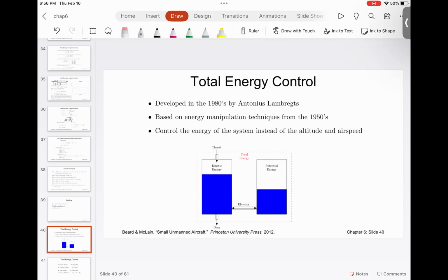That is, you fix the value of KD, and then adjust the KP so that it gets to the desired response. Okay, so total energy control is based on the Lyapunov technique. I'm not going to talk about the math behind this technique, because it is shown that in some cases successive loop closure yields better results than total energy control.